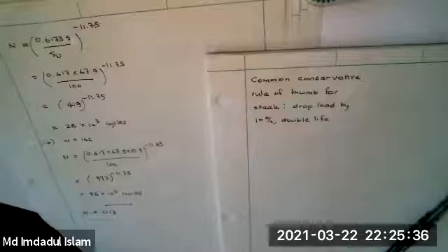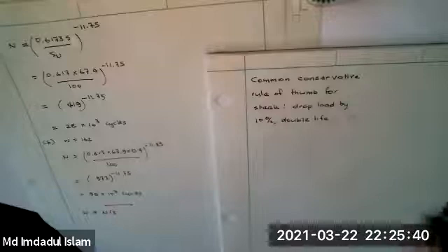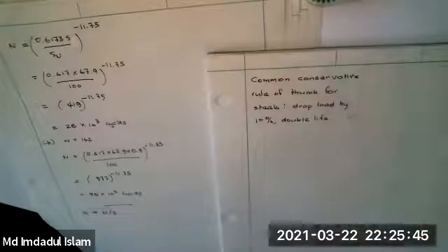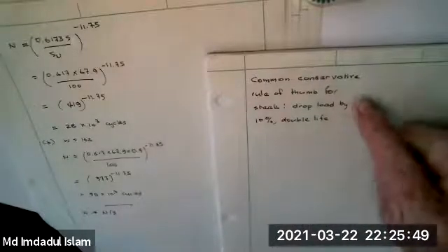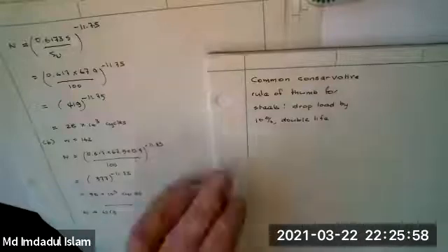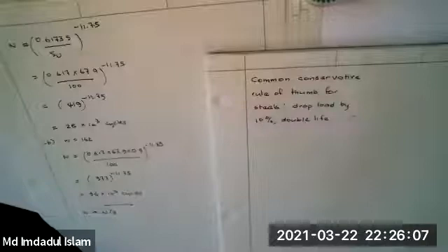But it takes more. This was just a preliminary design I did with a student. It should be done more consistently and carefully by testing. When you do that, because this is conservative, you actually find that the life increased more like a factor of 10, which would be 3 times 3. So there's a handy rule: when you see something that hasn't got enough life, it's not too bad, and you want to double it, just drop the loads by 10% if you can, for steel.